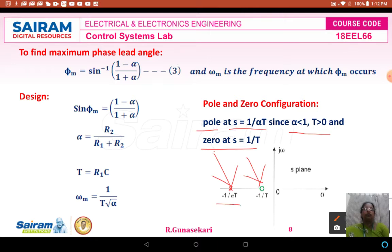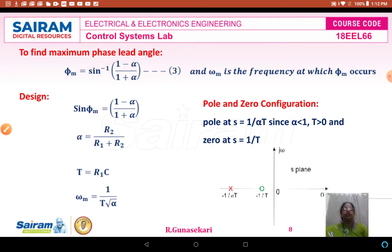So here the pole is minus 1 divided by alpha T, and the zero is minus 1 by T, because this is the positive side and this is the negative side, that's why we mention the negative. So this is the pole-zero configuration of the lead network.